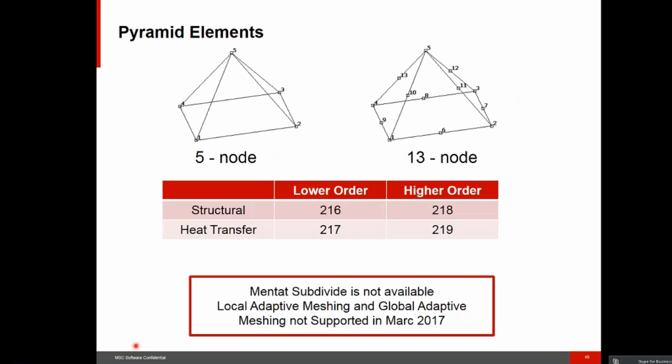And it's important to understand these are not a conventional hexahedral element that has been reduced to a prism element or to a pyramid element. It is a new element, with its own interpolation functions, so that we do not get a singular field in this area. The elements can be used for either conventional materials, and they can also be used for incompressible type materials.